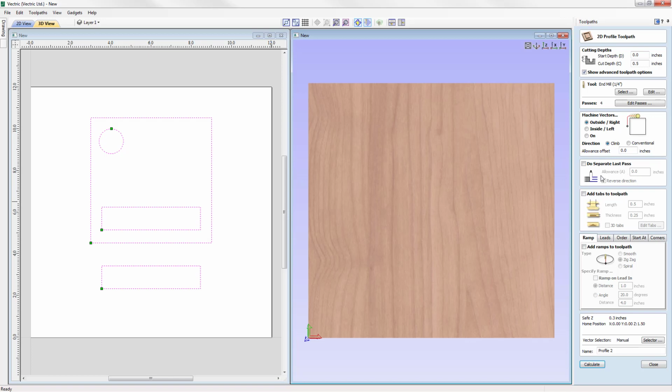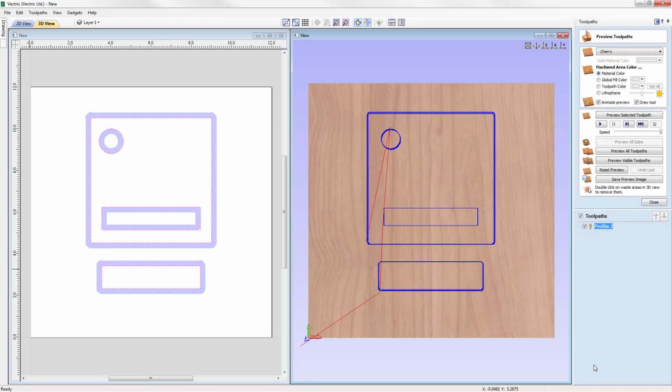And by doing this, we're keeping the tool away from the finished part by a small distance, and then we can remove the fine shaving of the allowance across the full depth with a separate last pass. So you may want to use this to eliminate witness marks created from each pass depth where you've cut down in stages. So let's switch this option on and we'll put in an allowance of 0.01, so a very small allowance here, and then we could go ahead and press calculate.